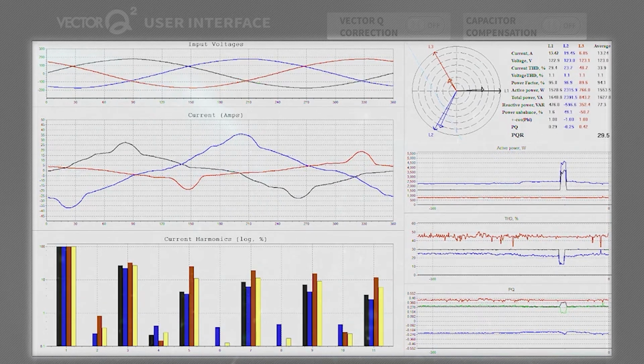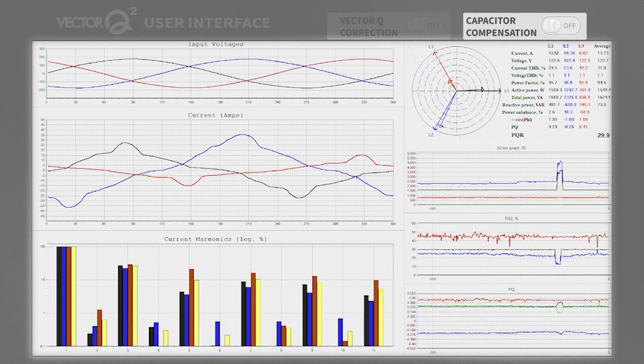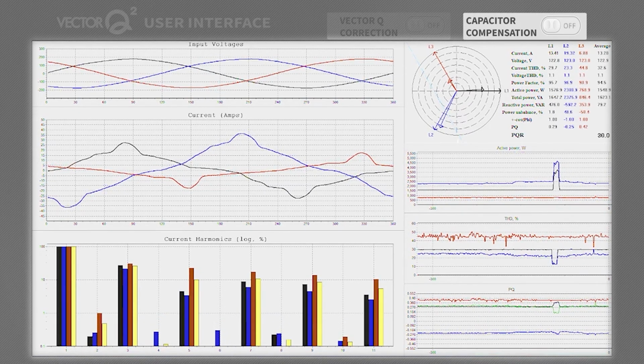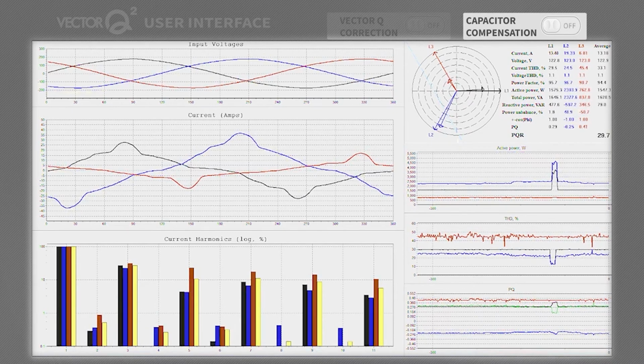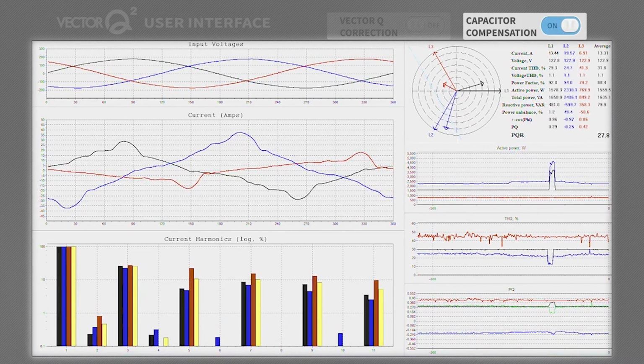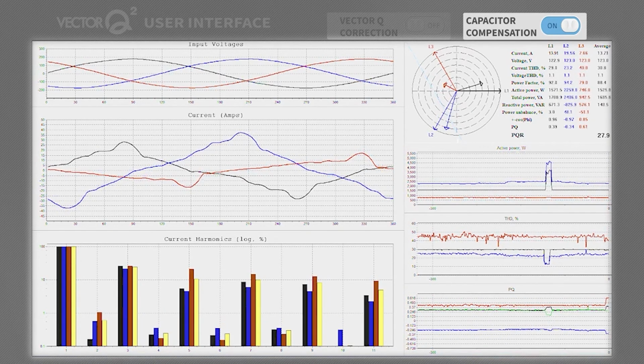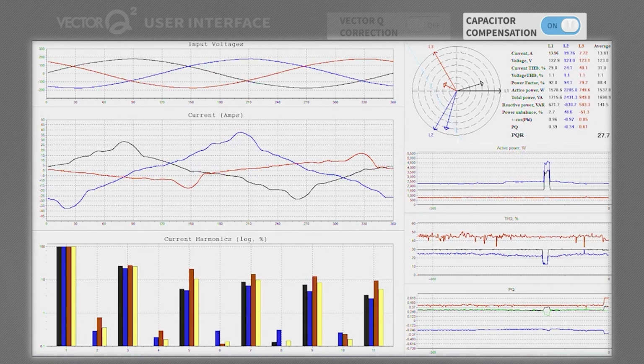Many modern power compensators lack the embedded intelligence for visibility, meaning they lack the ability to perform precise electrical corrections in real time. Instead, they rely on compensation. To demonstrate compensation, we will turn on a bank of capacitors. See the phasor diagram as all 3 phases shift equally. If this amount of compensation is needed for a relatively static load, this would have a positive effect on energy flow. This is in no way correction.